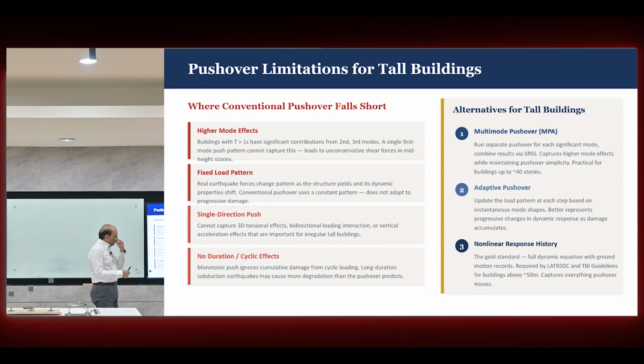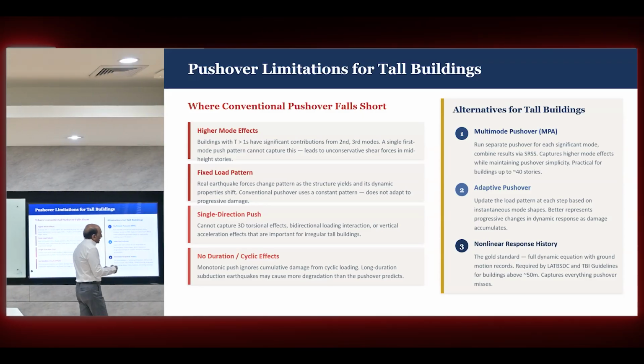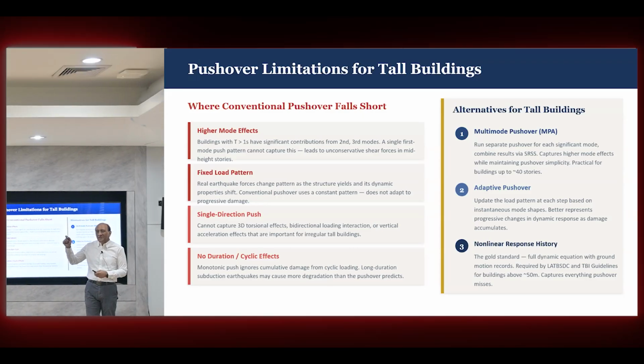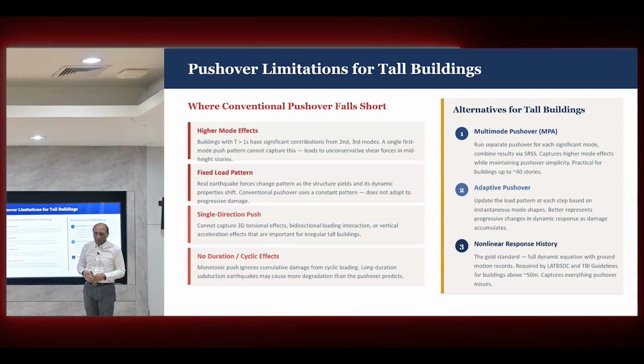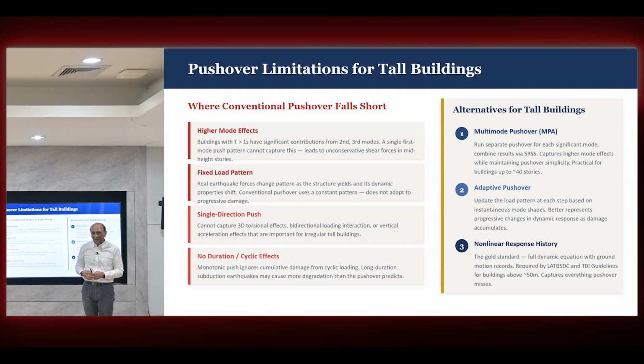Adaptive pushover changes, it updates the load pattern at each step. So you don't use the previous load pattern. You start with the load pattern, but it updates the load pattern based on the deformation. So it adapts the load, not just use the first load that you started with.